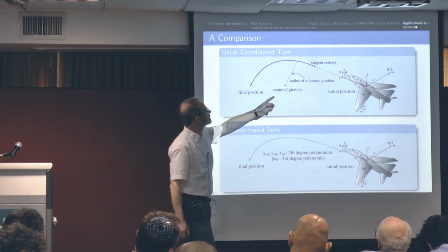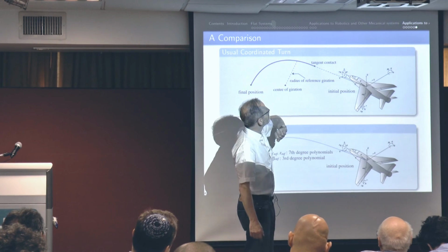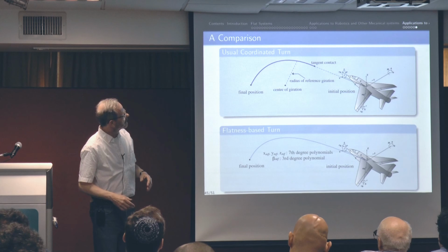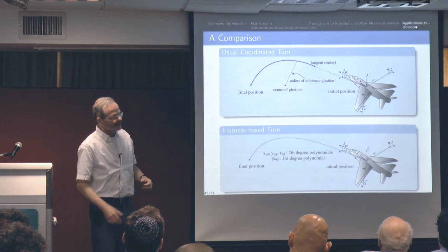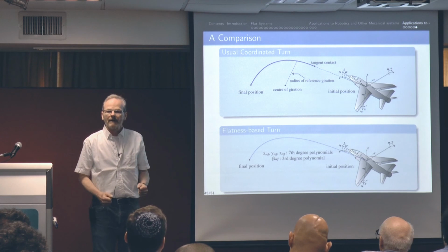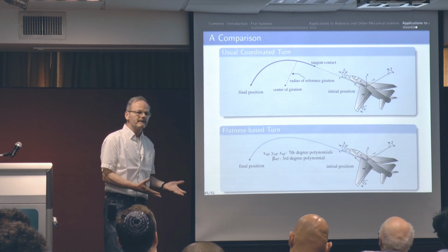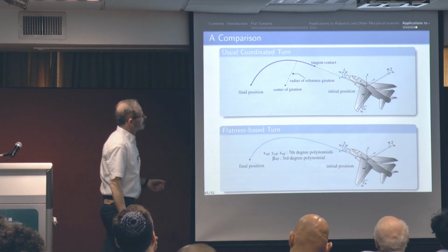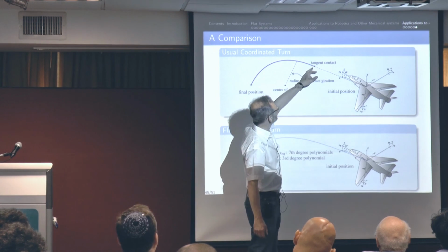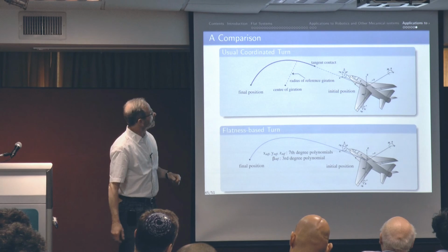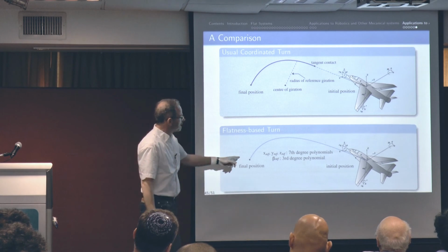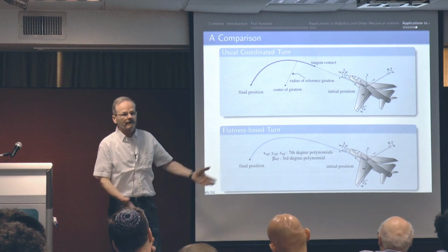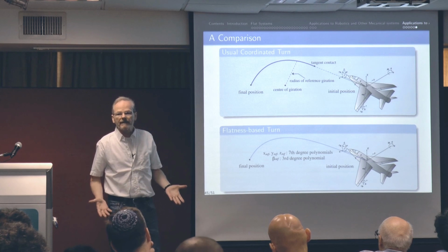And this discontinuity, if you're not cautious enough with the design of the gains in your controller, will produce some overshoot in the best situations, and maybe worse. So this point will be a source of problems. But here again, you design by interpolation a curve that you can follow without any discontinuity.